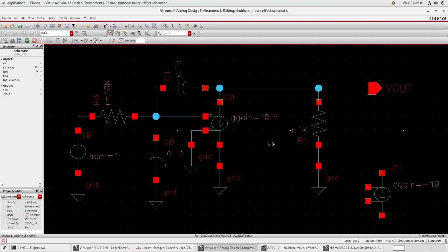You may recall that in a two-stage op amp, when we calculate the non-dominant pole, we short the CC and see the effective output impedance at the output port. Okay, so now theory and simulation are completely matching. So while calculating the dominant pole, you can account 1 by 2 pi, and Miller cap will be A times CC. And while calculating the non-dominant pole, you take CC only, and the only thing that will change is the output resistance.